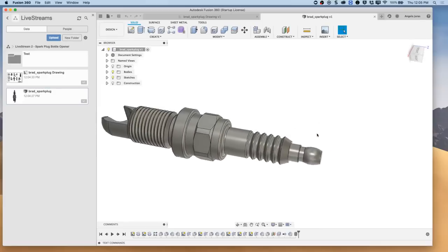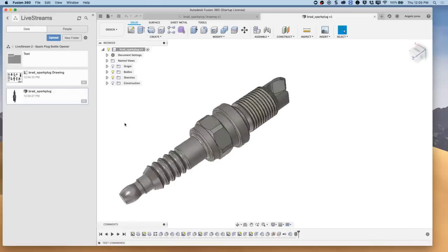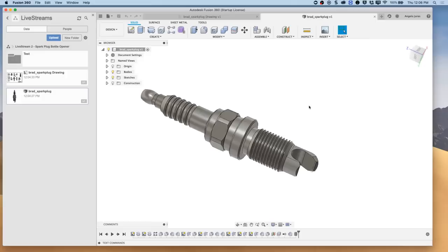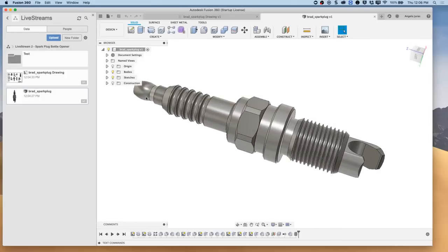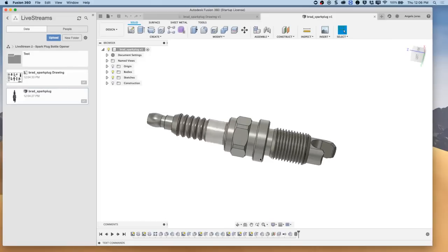One would think that you could hold it like this, chuck it on the left end, turn all of this, and then maybe re-grab it and do something on this side. But I'm trying to do this in one operation, so I can machine it starting here on the right side, work my way back to the left, and then part it off, and I'll have a completed part. So that's how I would make it.